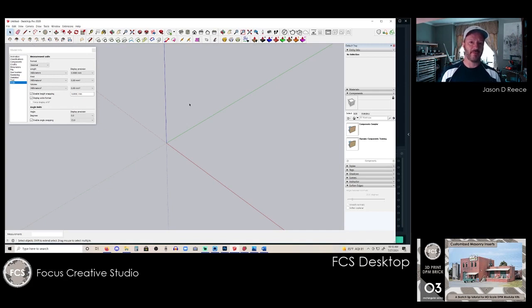We'll go through that. And then once we're done with that, I'm going to take the common brick file. That's just the standard brick insert, full brick. And we're going to run that through Lychee Slicer. And I'll add all my supports. I'll show you my support settings that I have set up and what works and prints well. I'll show you the support structure trees that I create that allow us to get great prints without warping, because that's a critical issue when you're trying to work with flatter prints.